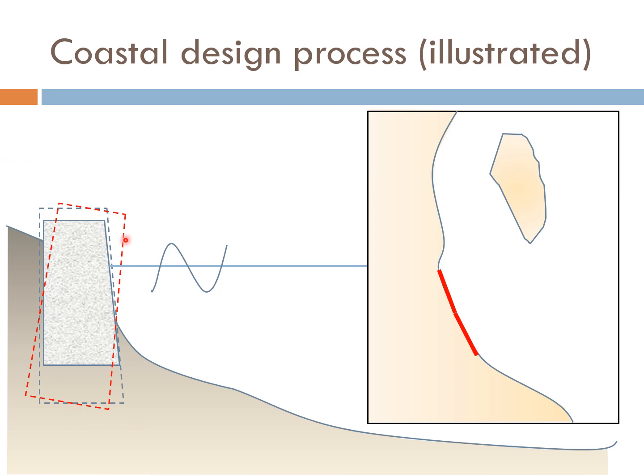Now, once this functional requirement, the dimension of the structure, has been designed, of course, again, we will have to make sure that the foundation is strong enough to bear the overall loading imposed. If that is not the case, then we will have to look at alternatives. But let's assume that right now this structure, the solid one here, is passed.